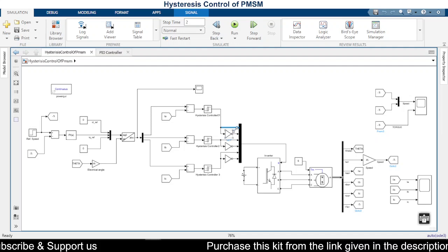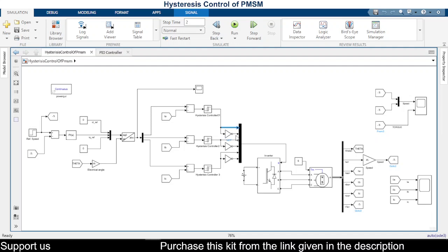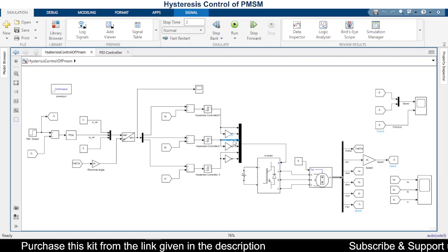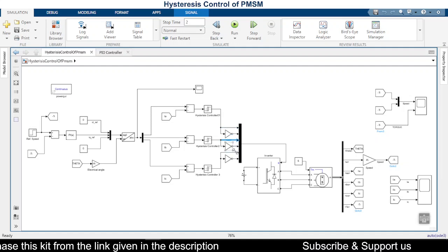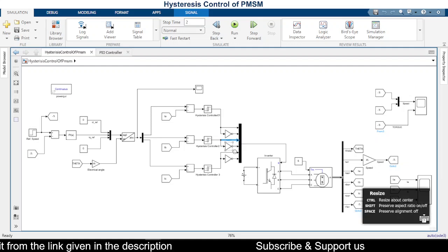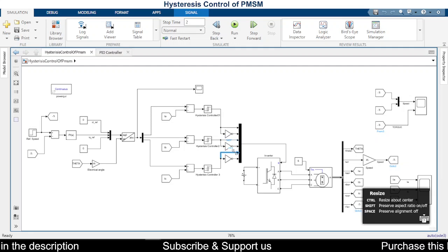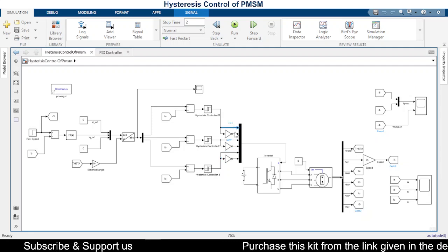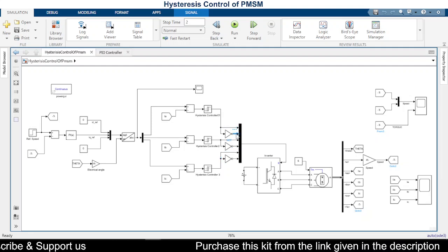So first leg and the second leg will have a phase difference of 120 degrees. If you see the phase difference between the first pulse of the second leg and the first pulse of the third leg, the phase difference used to be 120 degrees. And if you see the phase difference between this and this, it will be 180 degrees.